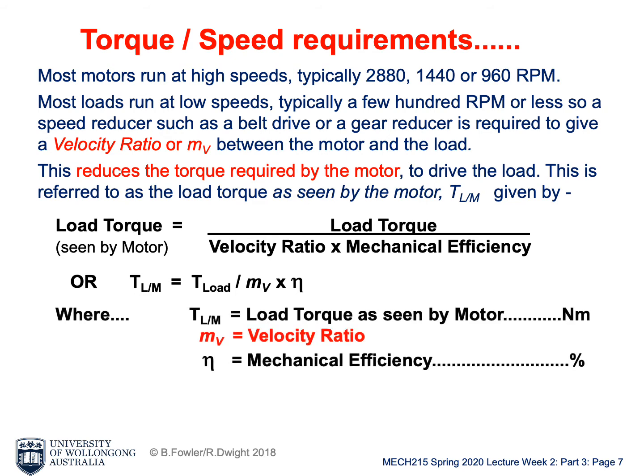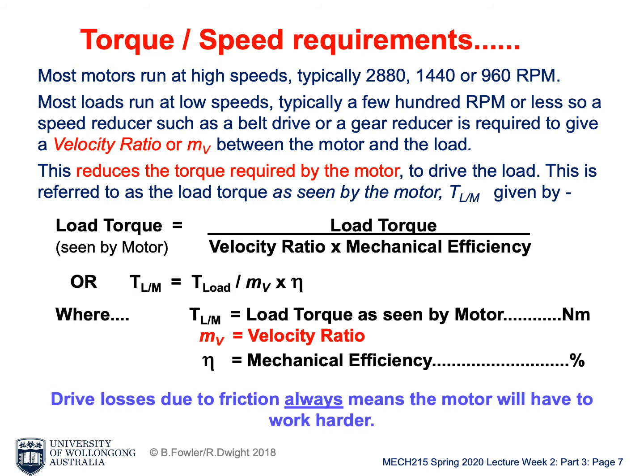The efficiency depends on your gearbox design, like different types of gear engagement will have different efficiency. And because the efficiency is always going to be less than 100%, you always have to consider that factor. When you design your motor, it needs to be a little bit stronger than the load power.